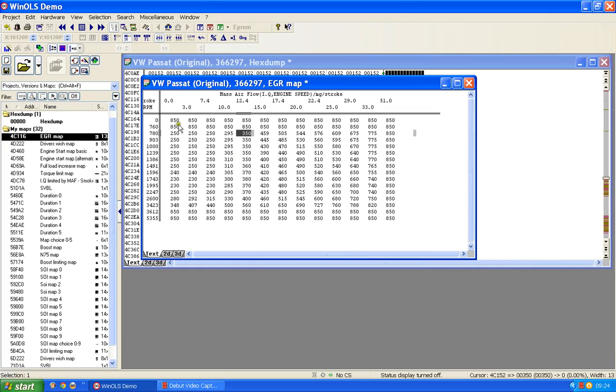And here we've got injection quantity, the factors have been added, and here we've got rev per minute, and you could say the factors have been added, although of course in engine speed there are no real factors to add. And here we've got the EGR values, which of course are really the mass airflow values as detected by the airflow meter, and these have been factorized slightly so they are sensible looking numbers. Right, okay, let's just get rid of that highlight.